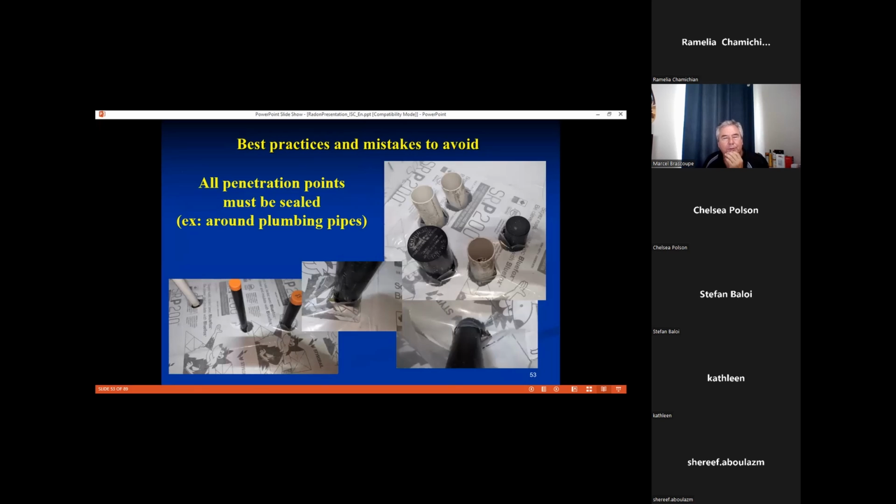Wherever any pipes, columns, or posts penetrate through that vapor barrier, that air barrier, you need to seal around that pipe. Like here, you can see there's a lot of big tears around the pipe there. The pipe's going through it. You can see they just took a knife and just cut through the membrane around the pipes. Now, if you don't seal that properly, a lot of radon is coming in around those pipes. So we have to take the necessary steps to seal around that.